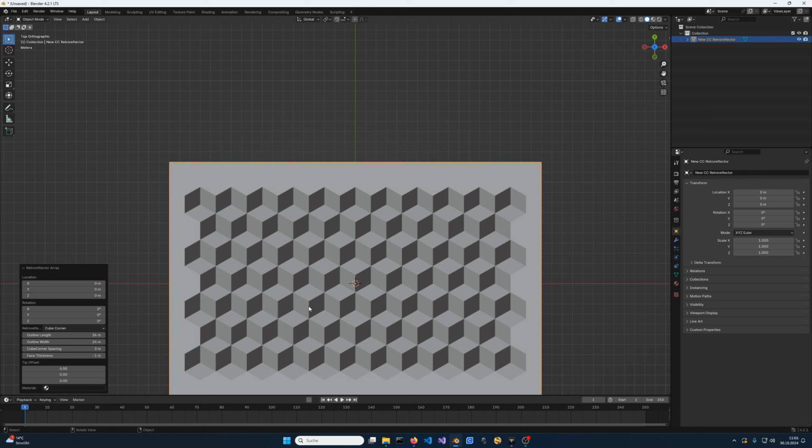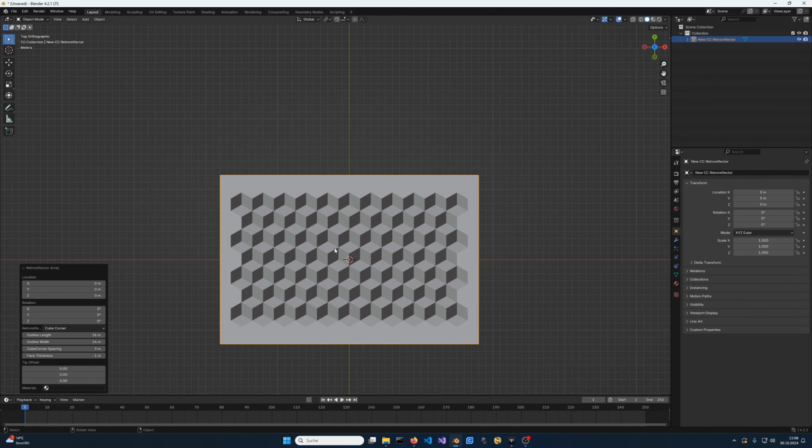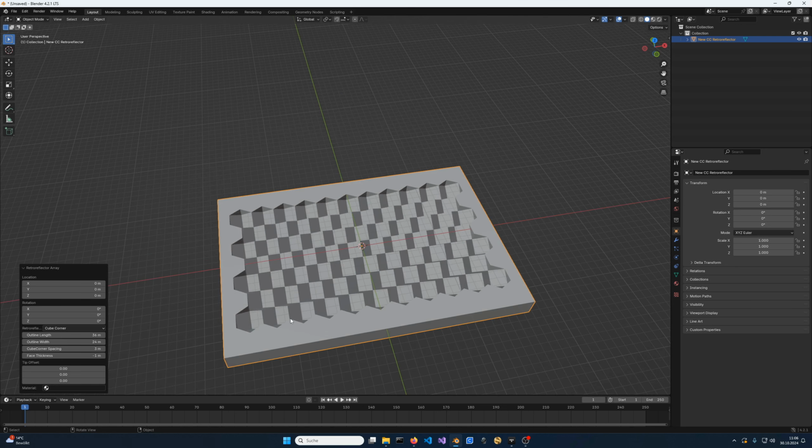However, these reflectors are not designed to reflect light perfectly back, because otherwise from the headlight of your car the light would be reflected back into the headlight and not into the eyes of the driver to make it more visible. So instead they are modeled with some slight deformation, which is available here through the offset of the tips. However, I cannot give actual guidance of how exactly these offsets would have to be chosen for you to create the real effect from a real reflector, but at least this feature is offered here.